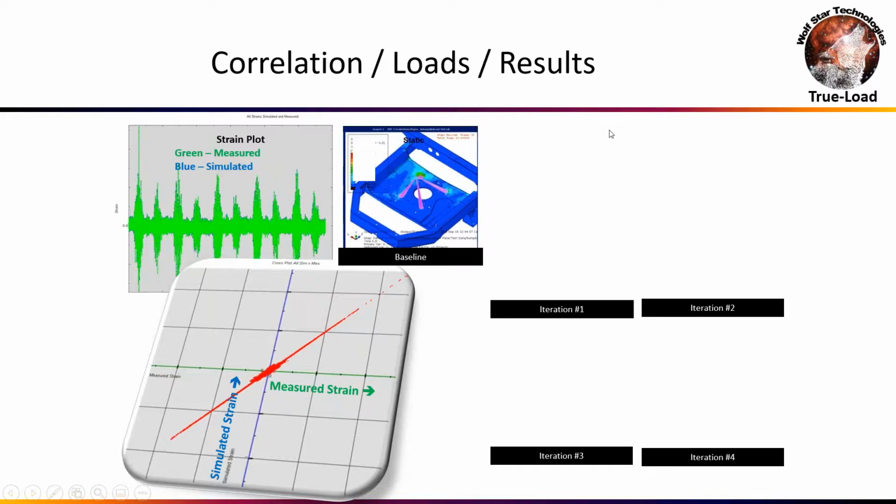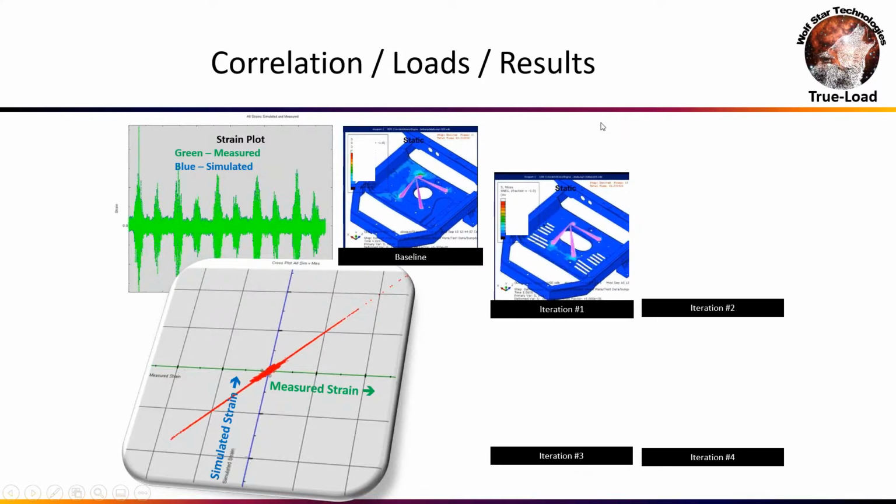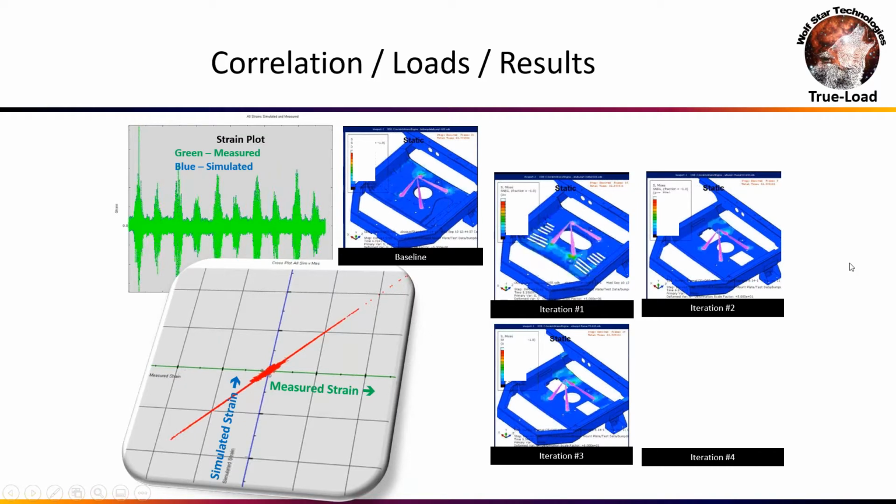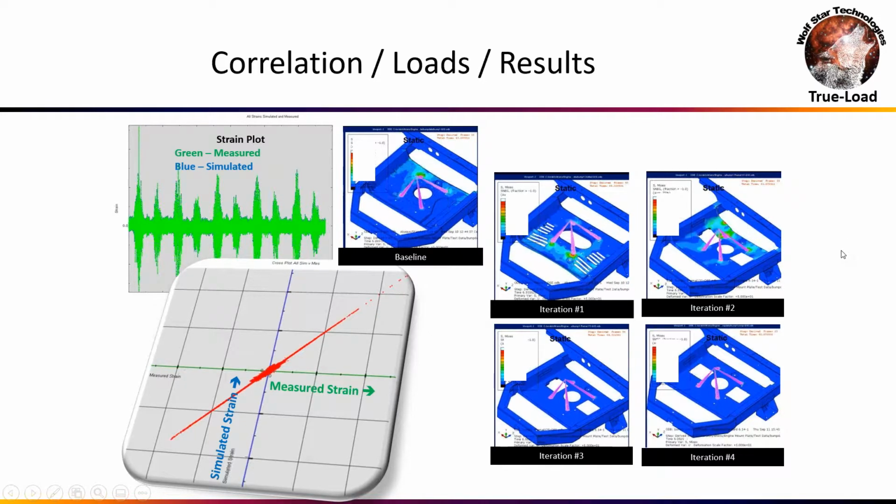And I said, perfect, give us that FEA model. So here's their design, and you can see the stress and strains that they're getting from this loading that we calculated. And working with the design engineers, we came up with a different pattern. So they basically came up with two larger holes, and we had a double layer of sheet metal here riveted together. And while this worked fantastically, the manufacturing guys hated it. So we had to go down to one layer of sheet metal. And so we iterated on thicknesses of sheet metal. And so by the end of the week, we had the design. The next slide, I'm going to show you durability results on this.